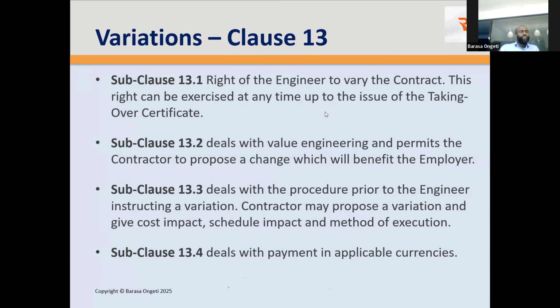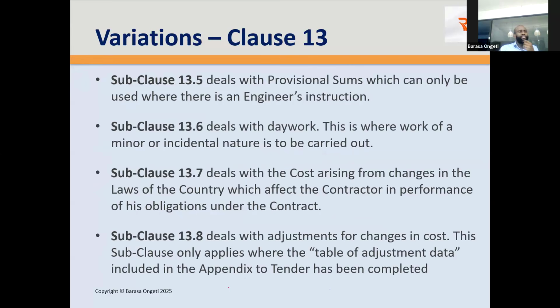So subclause 13.1, we've mentioned, right to vary. Subclause 13.2, value engineering. 13.3, procedure for instructing a variation. 13.4, payment in applicable currencies. 13.5, provisional sums. 13.6 deals with day work, which is where work of minor or incidental nature is to be carried out. 13.7 deals with cost arising from changes in laws.